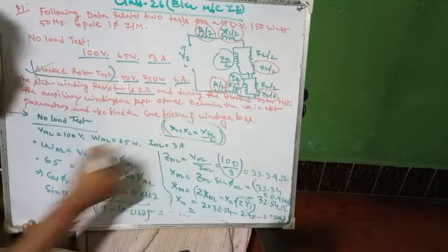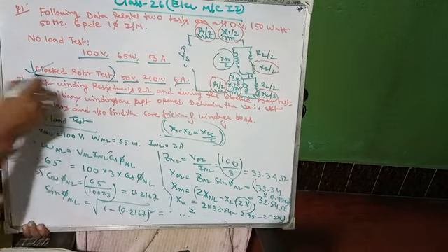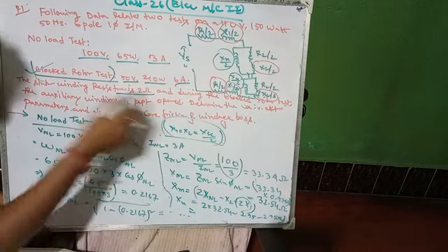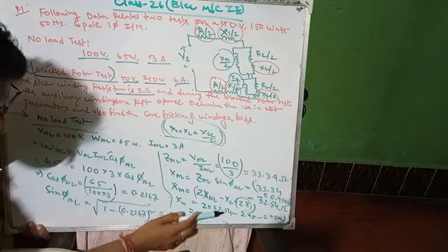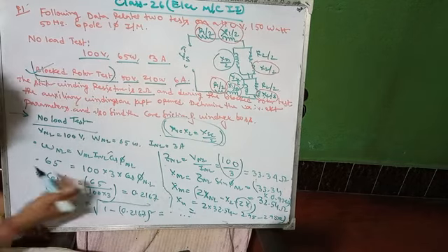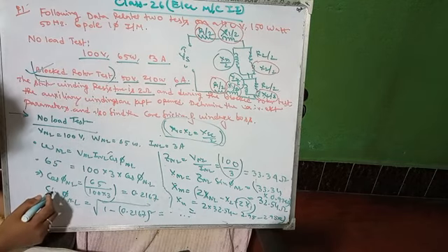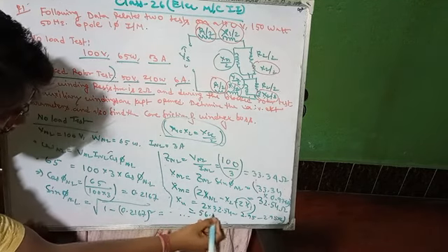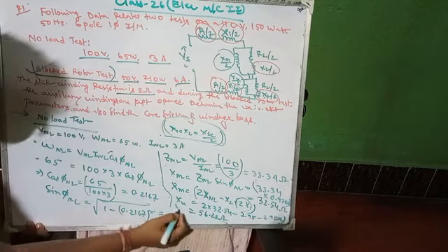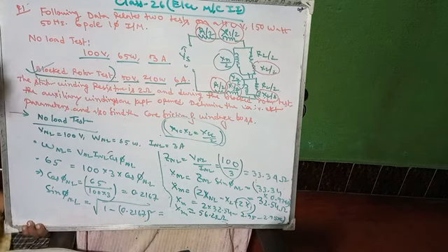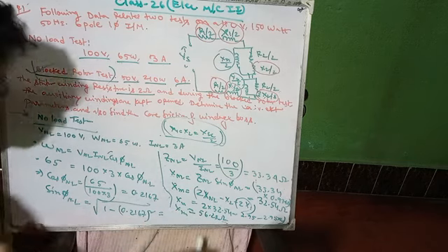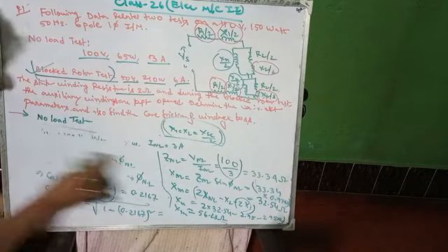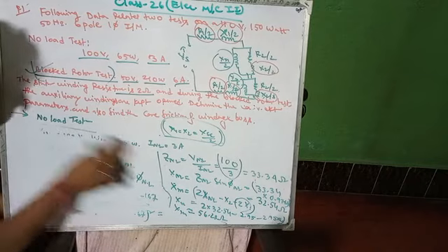So this is the concept. I have already calculated this in the block rotor test. From this same concept you can put in the values, and XM equals 56.23 ohm. Okay, so what will be the magnetizing reactance during the forward field and during the backward field?